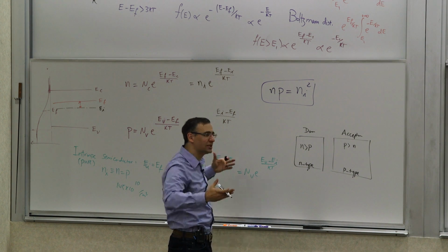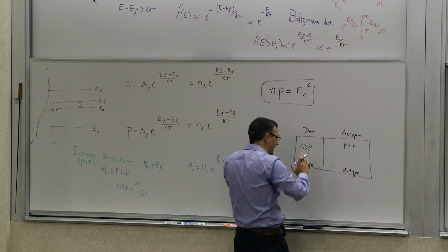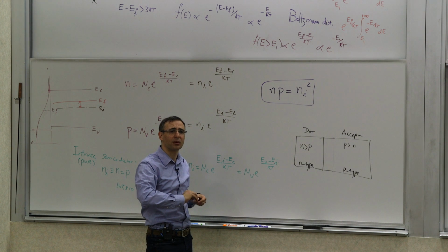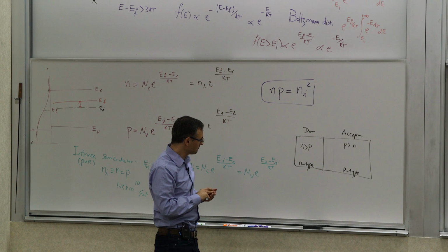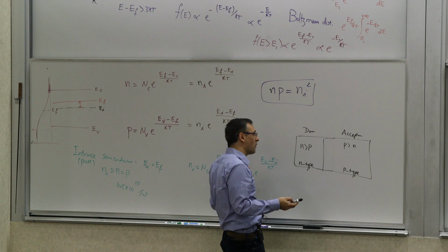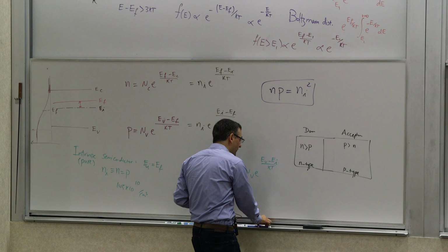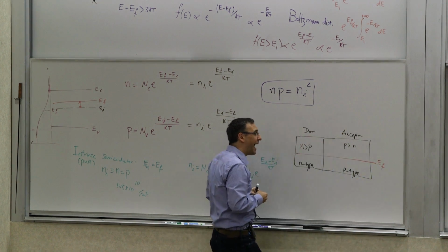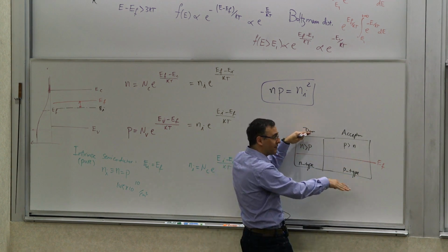Now, when you bring them together and attach them to each other, and you let it settle, which will happen very, very quickly in a semiconductor. The thermal equilibrium happens very quickly, and we'll discuss why later. Still, it's in thermal equilibrium. So the Fermi-Dirac distribution still holds. So you have the same Fermi energy across the whole thing. What happens, though, is that the energy band diagrams have to be bent with respect to that Fermi energy.